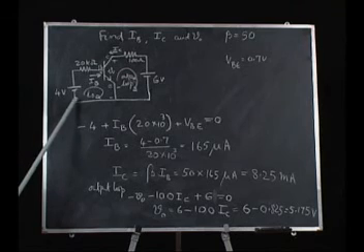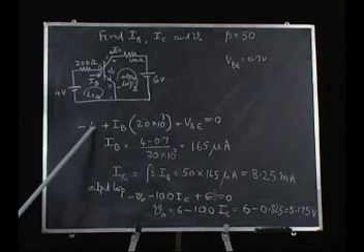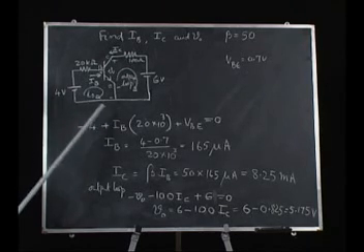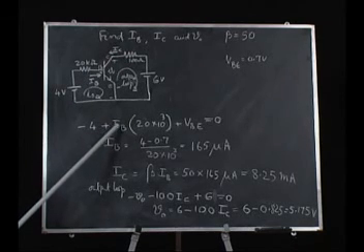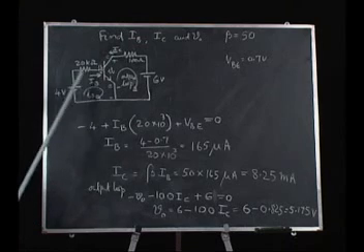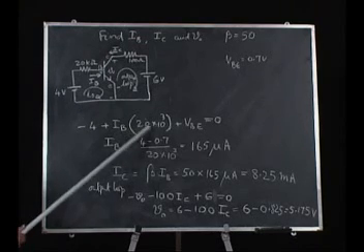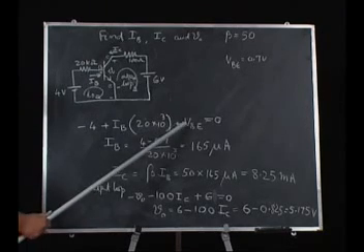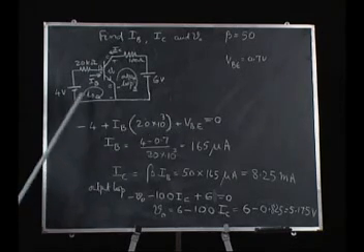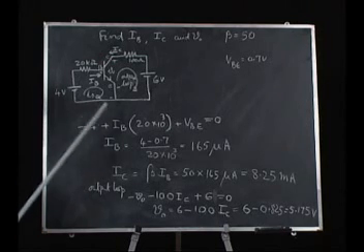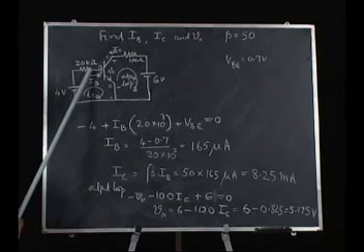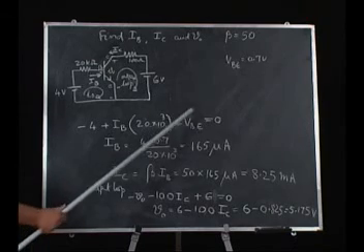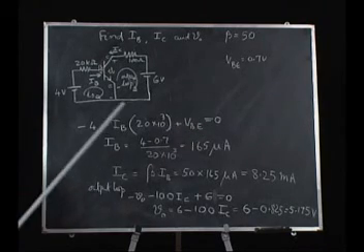Here there is a voltage rise, that is why it is minus 4 volts, plus there is a drop here, the drop is the base current multiplied by the resistance. The resistance is 20 kilo ohms, that is why we have written 20 into 10 to the power of 3, plus there is another drop, that drop is VBE. So, the total voltages, the voltage rise plus drop plus drop, form one mesh.